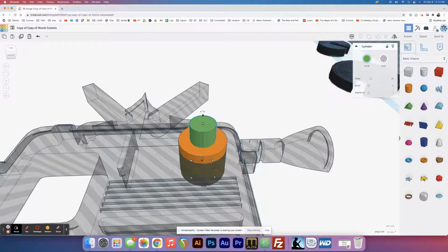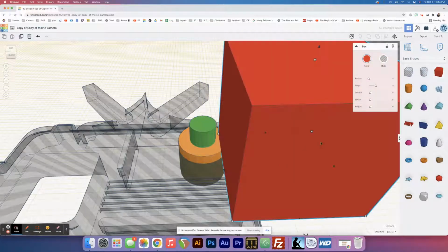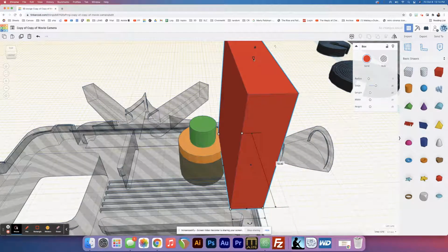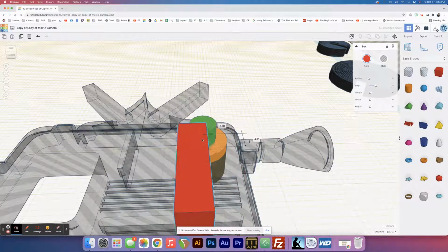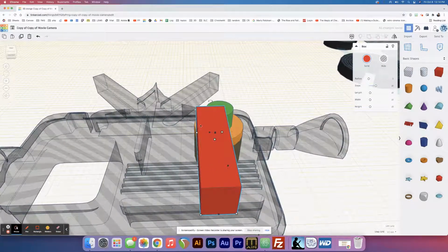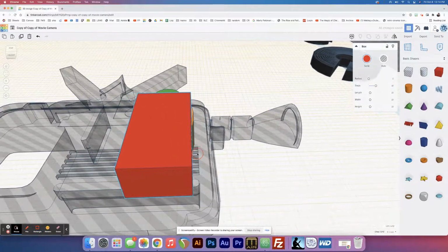And for that, I'm going to use the work plane placed on this surface. That way I can drag a shape like this onto the screen. And let's make it skinnier. Bring down the height. And let's get in alignment. I'm going to want it to be as close to in alignment with that orange edge. Probably have to go back down to 0.1. So left arrow. Yeah. And then bring this over and shift right click drag.